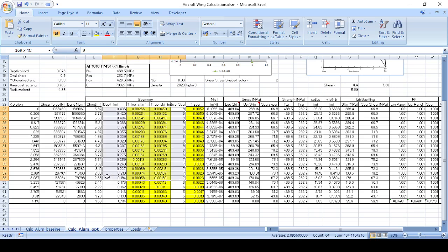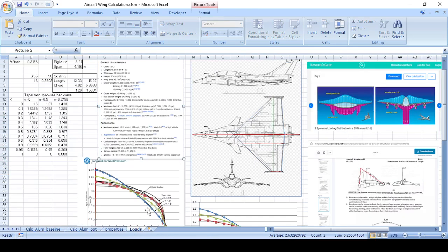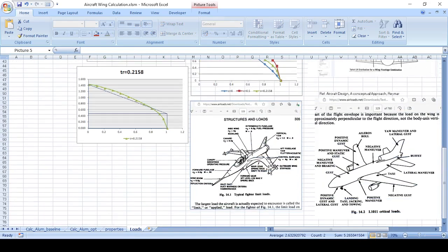Again, it's primarily the inboard area, because the outboard area is not actually sized. The loads are quite low for the outboard, and also the outboard area is not sized by wing bending. It's going to be more a stiffness driven design. As you can see here, outboard is wing stiffness, inboard is the bit that we're going to be using the maximum MZ of the wing.